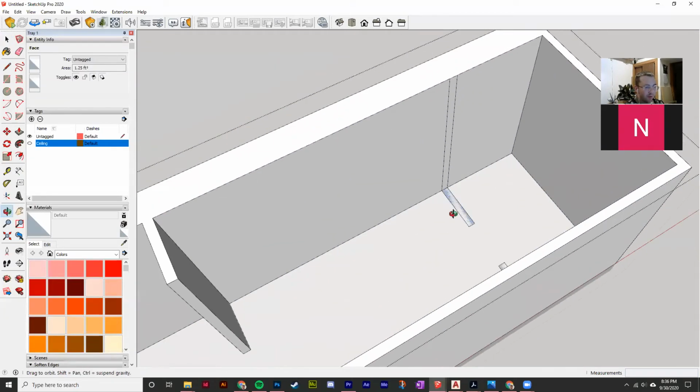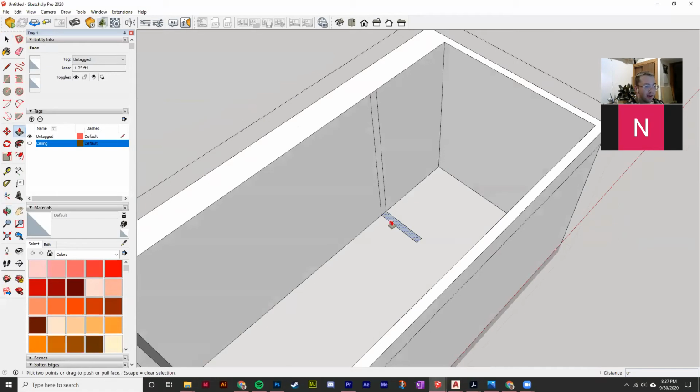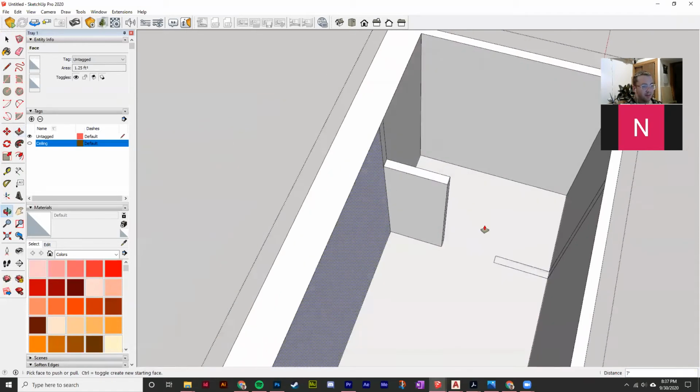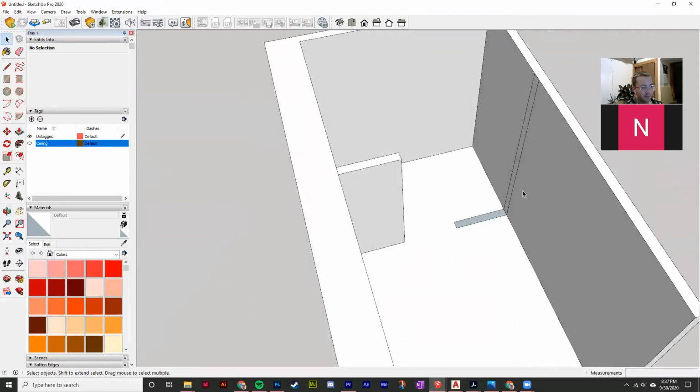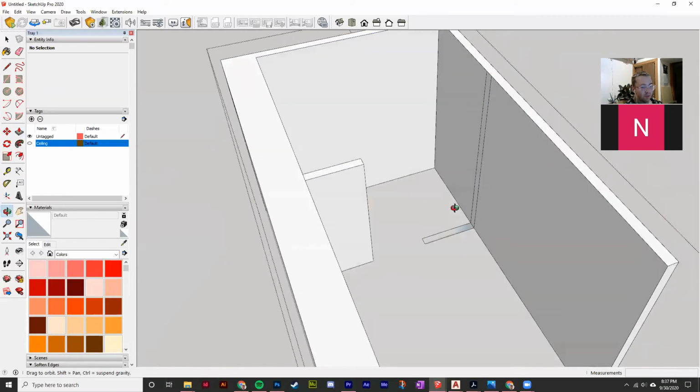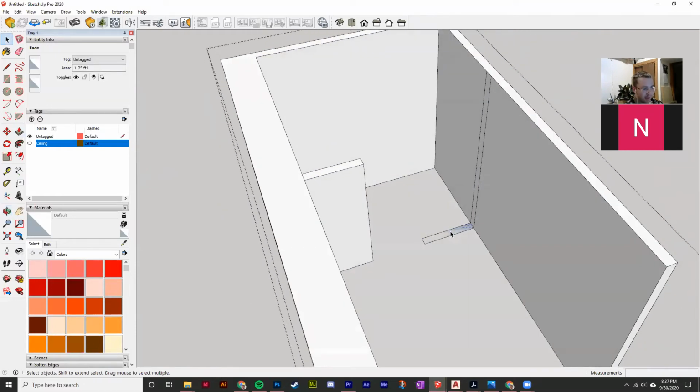So I'm going to go back into my walls, and I actually have a lofted section of my apartment. So these go up about 7 feet. I'm just using my push-pull tool, the shortcut for which is P. So I'm just hitting P, making sure I'm clicked into my wall group, or clicking over here for push-pull, and then just clicking and dragging.